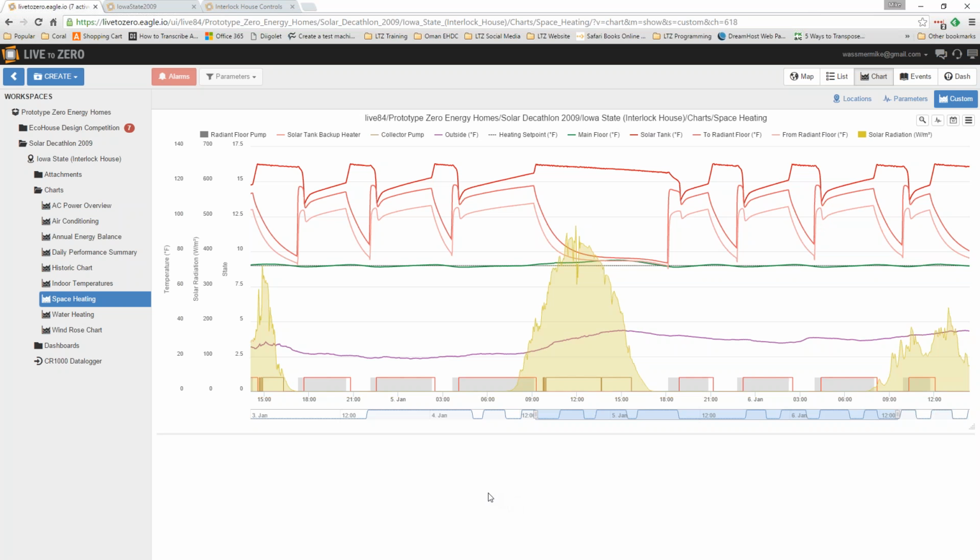is that when the system turns back on, it's staying on continuously, and all mechanical and electrical equipment likes to operate continuously. Especially not so much this system because it's 100% efficient electric heat. So it's just as efficient when it turns on and off as it is when it stays on all the time. But all mechanical and electrical equipment has a shorter lifetime when you turn it on and off more. So yeah, it's good to